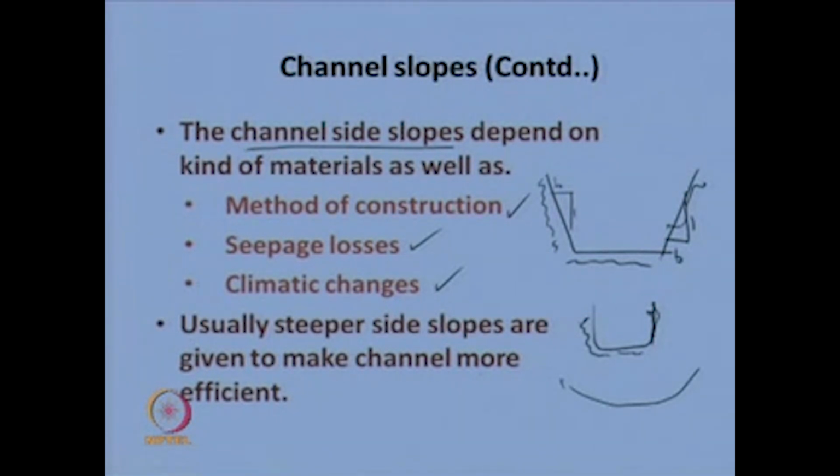Usually steeper side slopes are given to make the channel more efficient. We will discuss this later today. If the side slopes are steeper, that channel is able to carry more water compared to non-steeper side slope channels. So, those things also come into the picture.